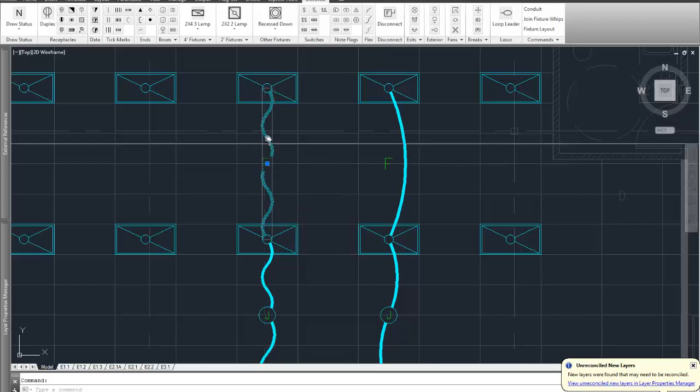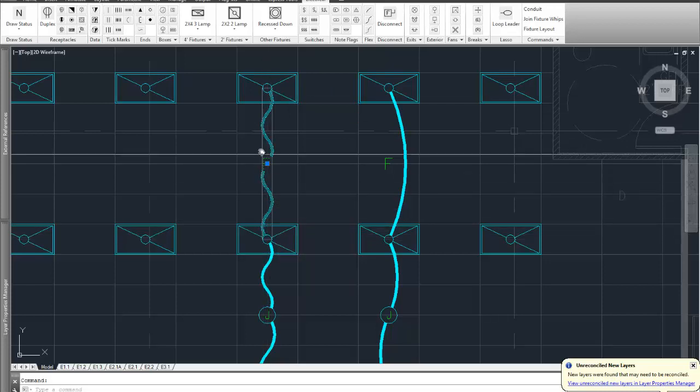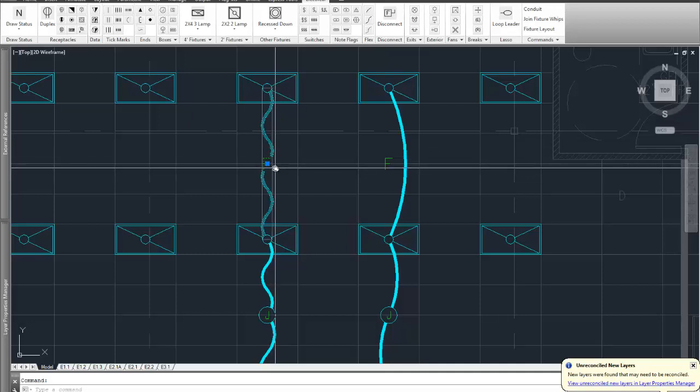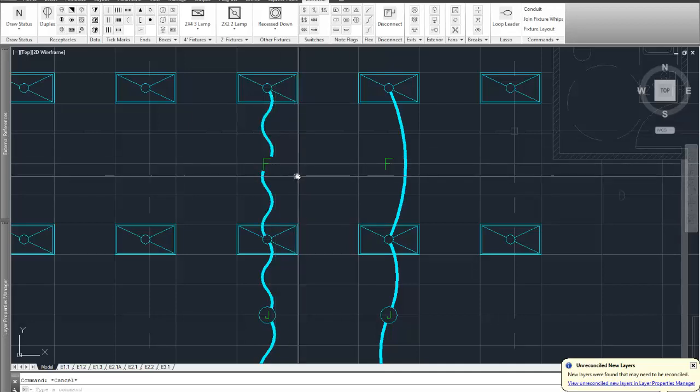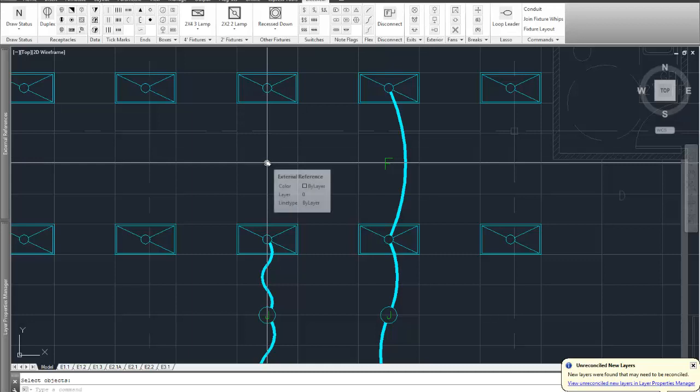The F, the whip is actually drawn the entire way, and then the F is placed, and then the whip is trimmed, and then they're grouped together so that if you're coming through and editing and you're erasing things, you can click on it one time and it's erased. If you don't do that, drafters with lower experience will, you'll find random Fs floating throughout your project, and it's just a mess. So we group certain things, and this is one of them.